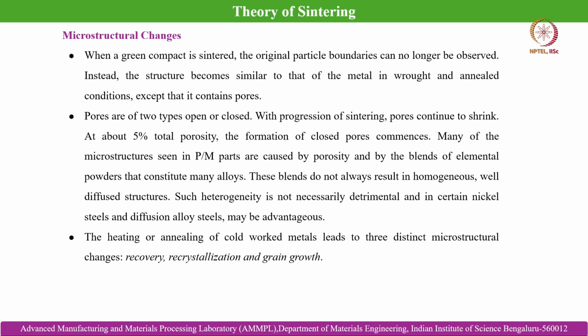Solid solution formation happens during sintering when we mix two powders together, consolidate and finally sinter. In those cases, the kind of porosity that evolves because of the two phase microstructure is also different, because of the different densification rates of the powder particles mixed for in situ alloying.